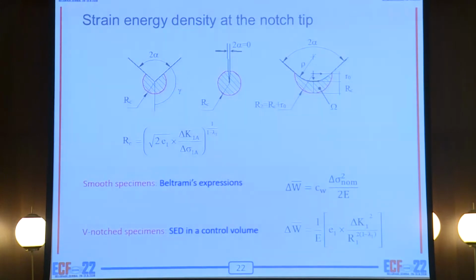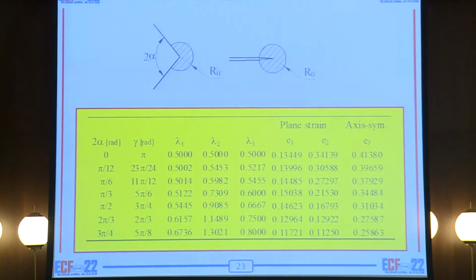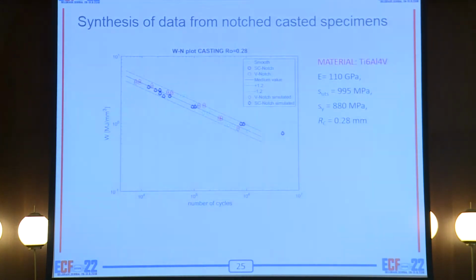So you don't need to use this analytical method. You can also simply get the SED values from Abaqus, ANSYS, or any other FEM software, which is quite easier than calculating it by analytical formulations. These are related to the analytical formulation and experimental validation.